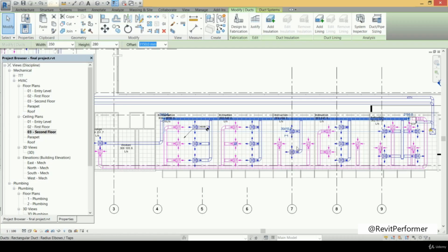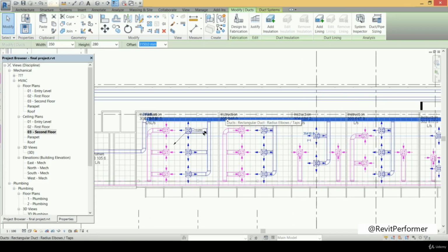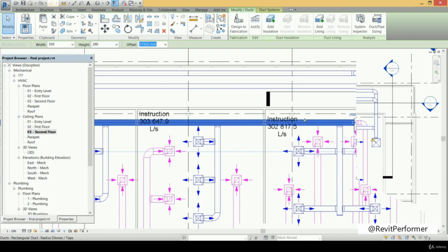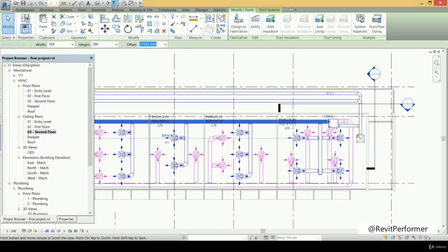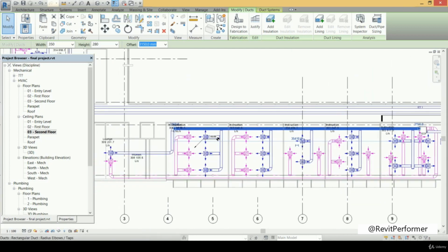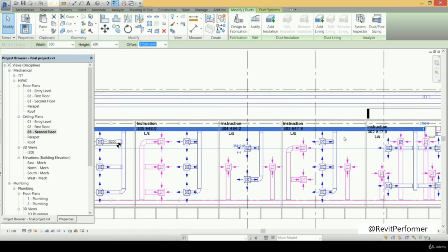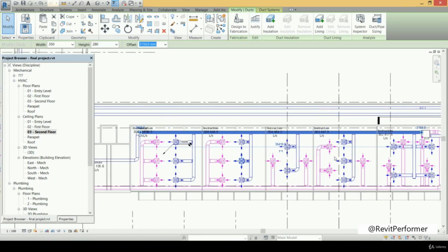So what we want to say is that although we have only one duct, this duct must be sectionalized into some sections, and each section will have different dimensions according to the airflow through it, according to the sections that this part of the duct will feed. And this means we need the size of that part of the duct to be larger than the size of the rest of the parts of that duct. So the part size will be larger than those parts size.